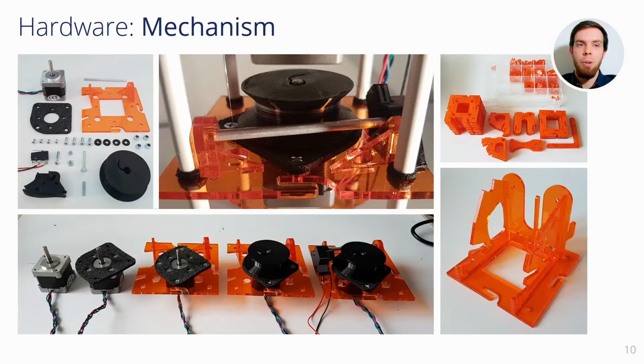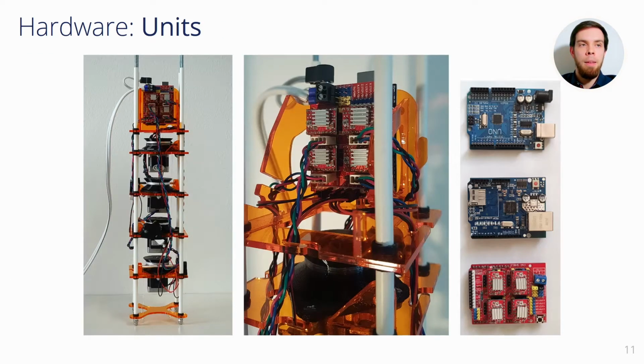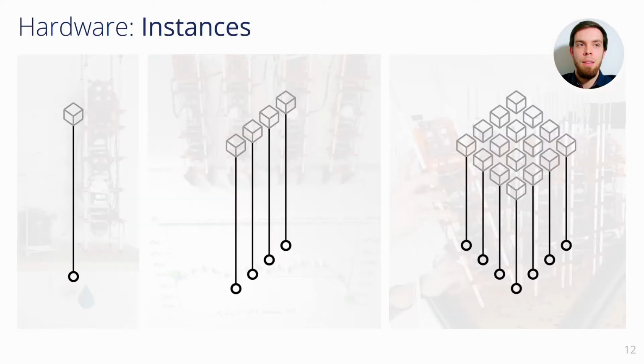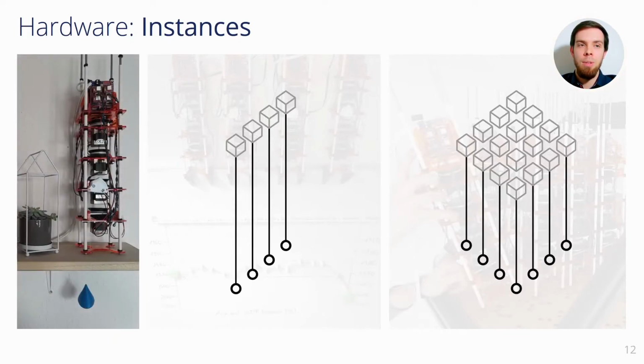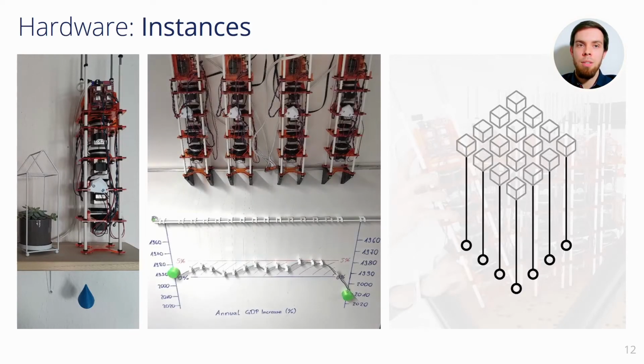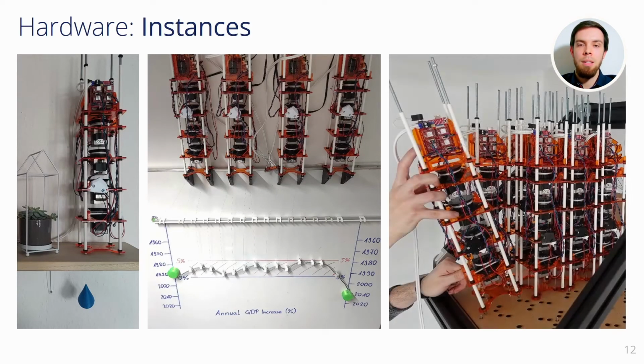They are made from laser-cut acrylic containing the motors, a limit switch, and a roller mechanism which uses a braided line to lift the attached element. As we want to achieve dense arrangements, we stacked 4 actuators in a motor tower to create these self-contained units. You only have to add power and Ethernet, and then you can actuate 4 elements individually. To prove their versatility in different scenarios, we applied these actuation units to 3 different physical setups. We have tested 1 tower in a home environment, 4 towers on top of a whiteboard, and 16 towers in a dense matrix arrangement with over 64 actuated elements.